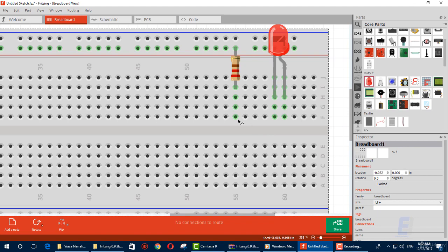Just like a real breadboard, the one that you have at your lab or at work, we can add small wires to make the connections we need. Place your mouse over a breadboard hole and observe that it turns blue when you touch that hole. This means that it's ready to start wiring from this point to any other point that you wish. Click the breadboard hole and drag the new wire to the desired location.